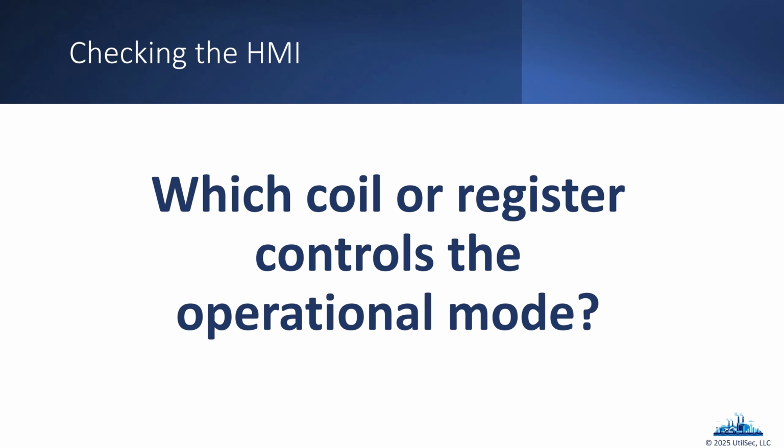Do you have a PLC that an attacker could connect to over an OT protocol like Modbus, Ethernet IP, S7? Make a change to a coil register to be able to take the PLC out of run mode and put it back before anybody notices.